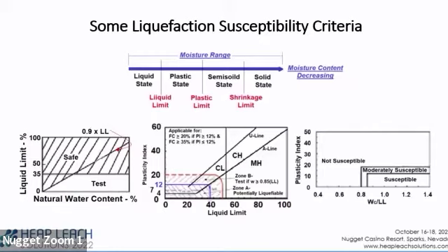And I promised a screening tool, and I'll dabble these in during the lecture. So one is, every soil mechanics lab in the world does Atterberg limit tests. And the most common Atterberg limit is liquid limit. This is the moisture content at which your material makes the transition from mostly solid to mostly not solid. And if your ore is anywhere near that moisture content, you need to do a lot more work on your project or figure out how to operate the heap so you're not up there. You don't want to be anywhere near liquid limit.